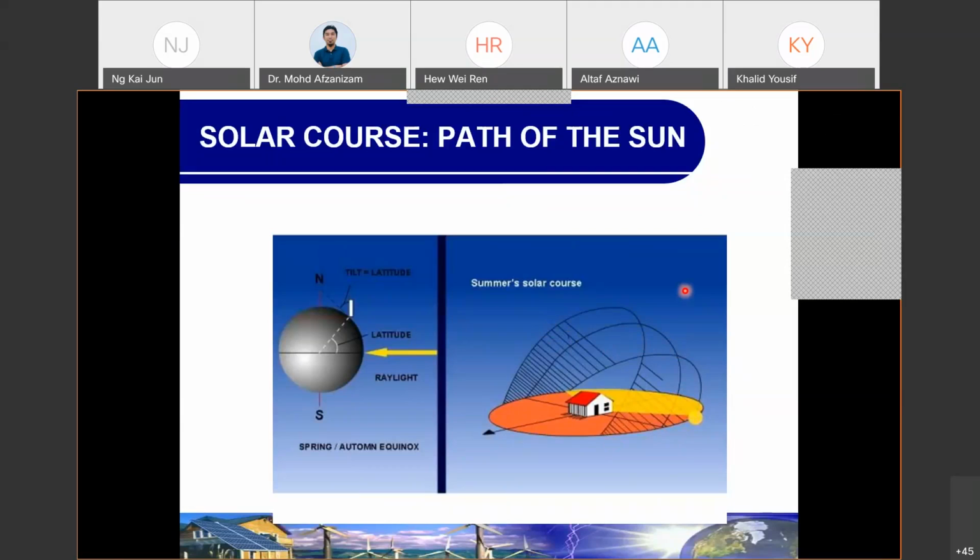That's why before we install the solar module or solar array, we need to assess the particular area to ensure that we gain as much as we can from the sun ray. Or else we might experience low irradiance, which leads to low output or low efficiency.